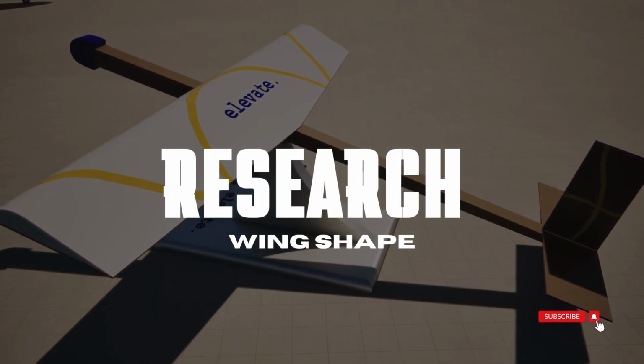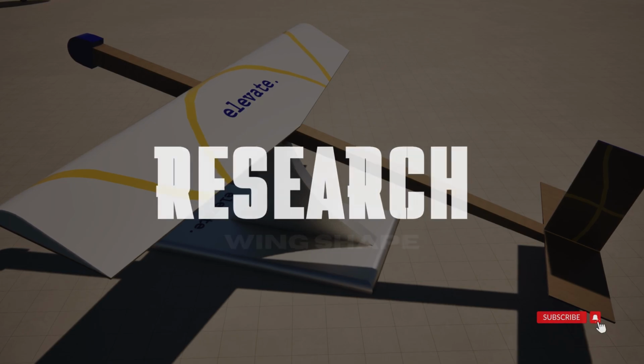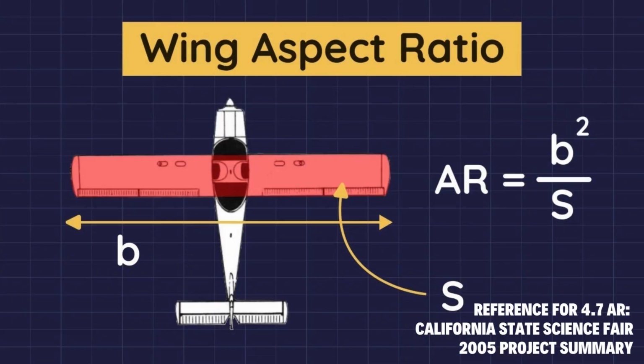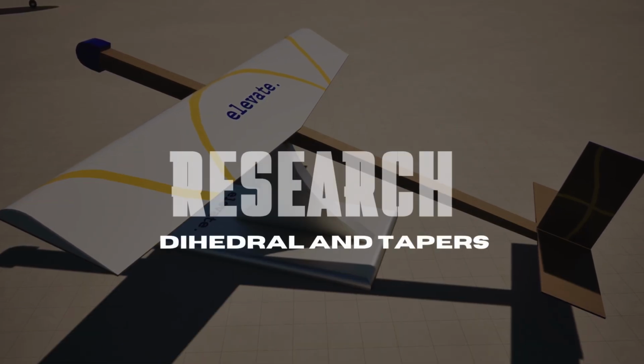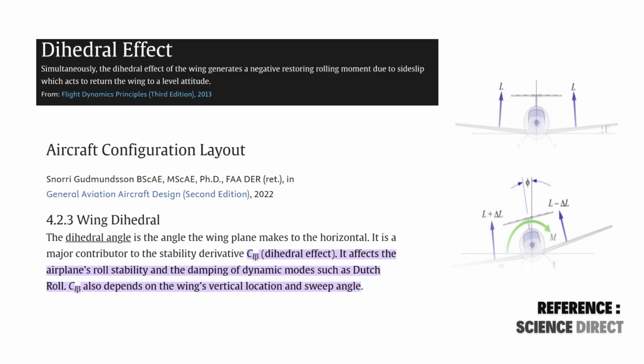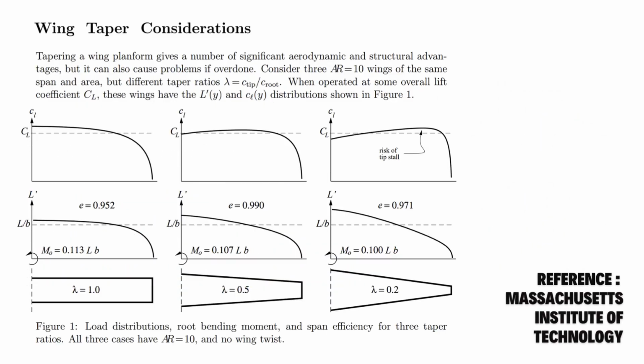For the wing shape, I learned about the trade-offs between drag, stability, and maneuverability between longer wings and shorter wings, and ultimately discovered my aspect ratio should be around 4.7, while the approximate angle of attack I should have on my wing was 3 degrees. I also found out about the dihedral effect and how it can make an aircraft more laterally stable, as well as how tapering a wing can reduce induced drag.